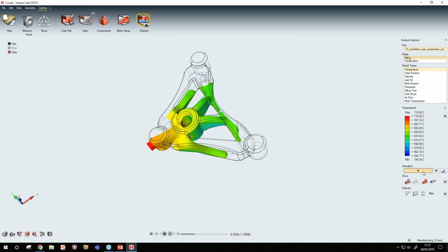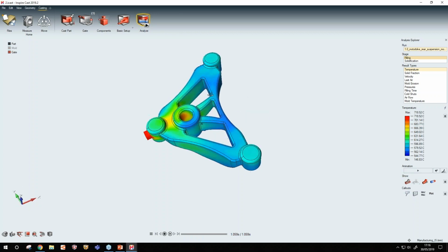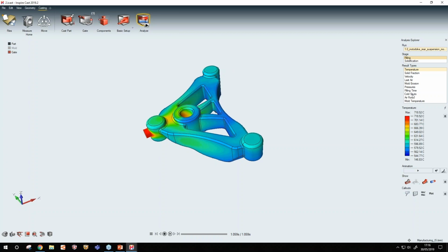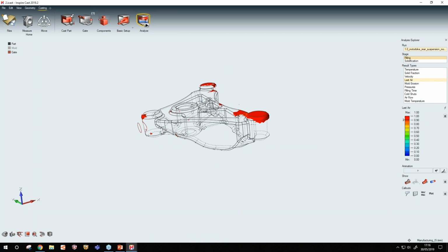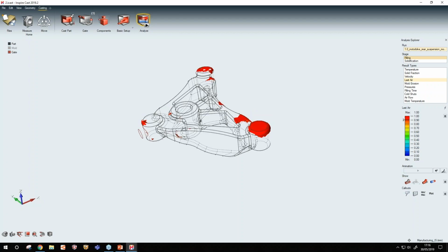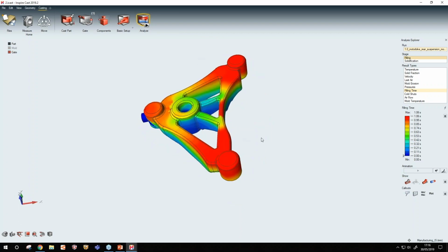filling time has changed. We now have more homogeneous values of filling time, not too many turbulences because the gravity is pointing downwards. We may have some air entrapment in this particular region, let's see, because of the evolution of the metal, but we can machine this part and remove these bubbles or impurities we will find after production. So let me see what happened with filling time. Filling time is much more homogeneous. That will allow us to avoid turbulences and entrapments.